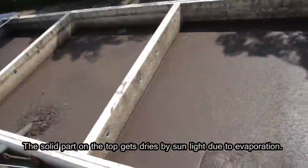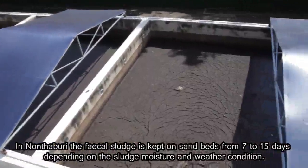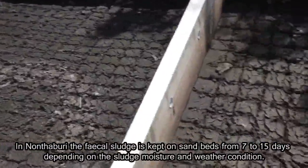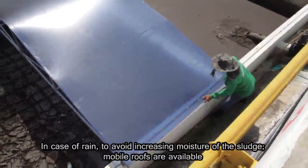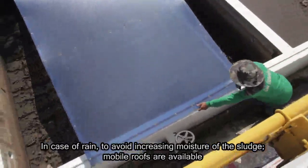The solid part on top gets dried by sunlight due to evaporation. In Nonthaburi, the fecal sludge is kept on sand beds from 7 to 15 days, depending on the sludge moisture and weather condition. In case of rain, to avoid increasing moisture of the sludge, mobile roofs are available.